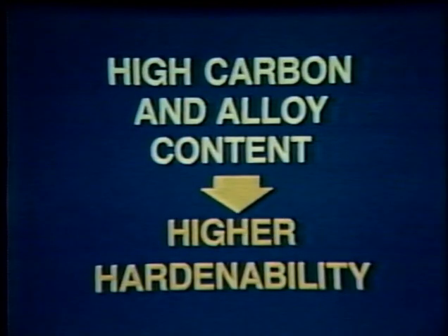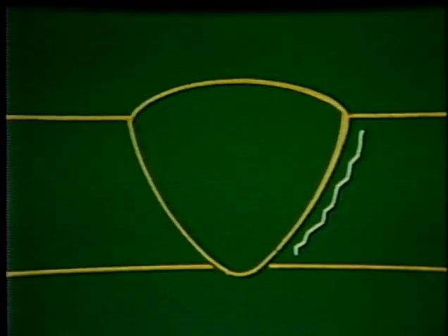The higher the carbon and alloy content of a steel, the higher the hardenability. Hardenability is the ability of a material to become hardened. High carbon and high alloy steels produce high degrees of hardness in the weld and heat-affected zone when the weld is cooled rapidly. This causes the weldment to be more crack-sensitive and therefore prone to failure in many loading applications.